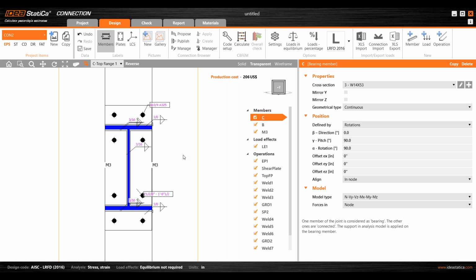Awesome. There was also a question about the use of the asterisk when it comes to the bolt placement. I'll just take this one. The asterisk is a shortcut to place the bolts. So using David's example, if you have 5 bolts that are placed at 3 inches from each other, then you can just do 3 inches times 5, and you will have those bolts all spaced at the same spacing. It's just a shortcut. You could just type 3, then space, then 3, then space, etc. That would be the exact same thing.